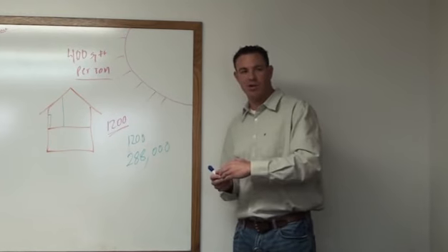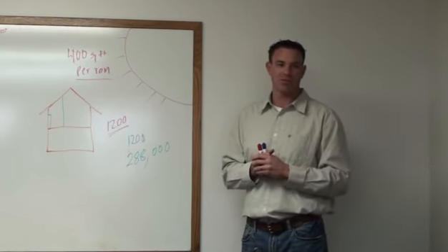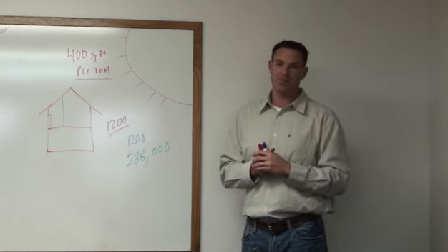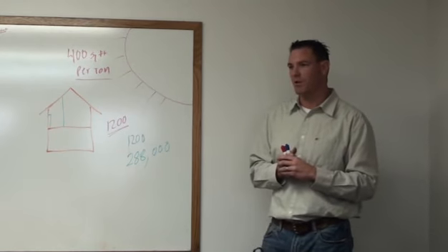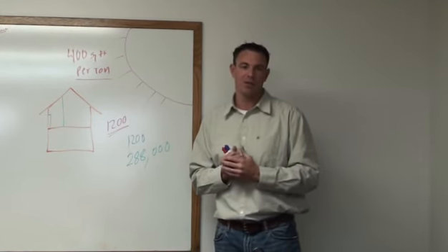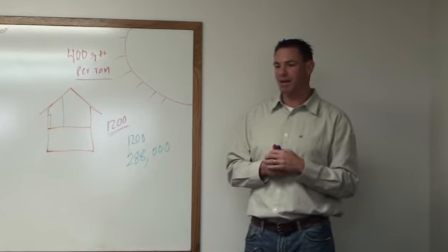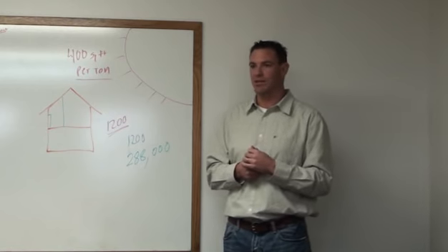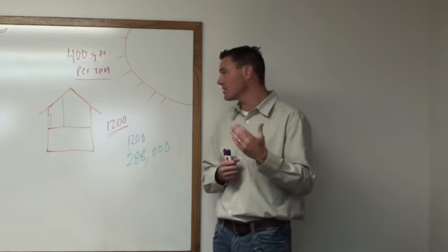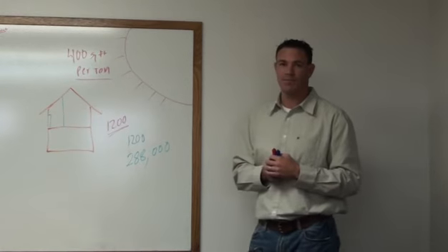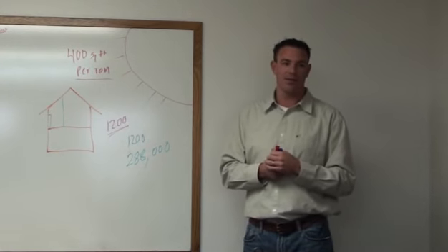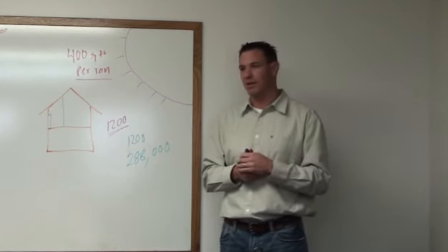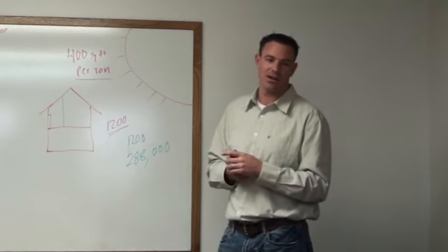If they take the same unit and transport it to, say, Steamboat Springs in Colorado, you've gone to a really high elevation. The air is much less dense. You're not going to get the same performance that you get at a sea level location. Most pieces of equipment are manufactured and distributed from a sea level location, and their performance data is most of the time written from a sea level location. So I would dare say that you could suffer a 100 to 200 square foot cooling loss depending on your altitude from point A to point B. So it's definitely something to think about, and ask that question when they call us, what is your altitude?